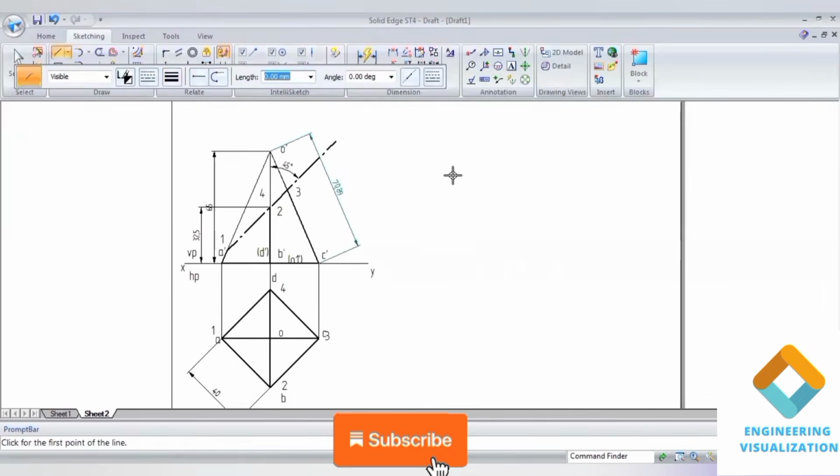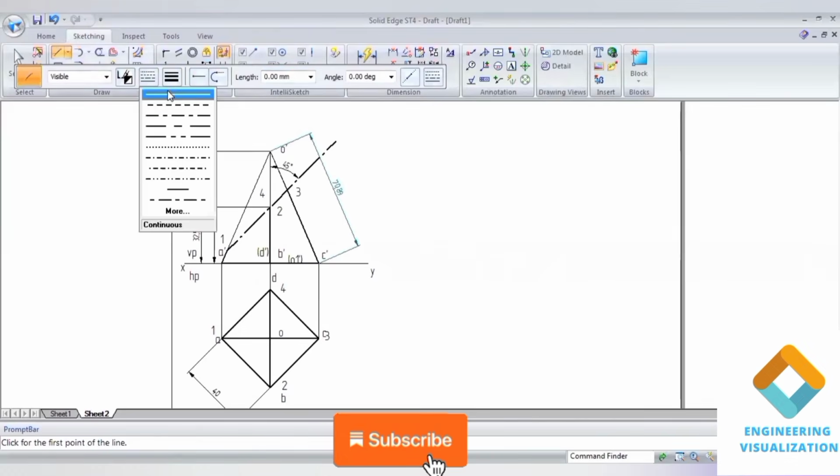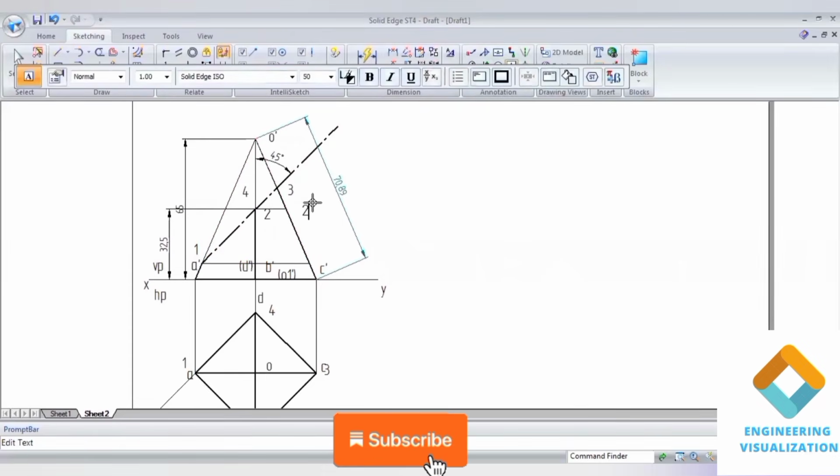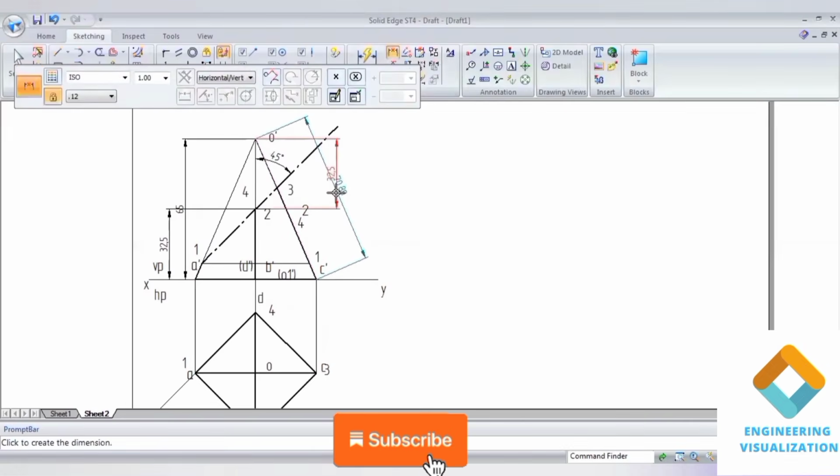For the same length, we'll be drawing a line. Now we need to transfer all these cut points onto the slant edge length. 1 and 4, this is an important step, guys. You should do it. 2 and 4, and this is 1. 3 is already there on the slant edge. You need to measure these lengths because we need to cut the arcs on the slant edge when we are drawing the development. We should know these dimensions. The slant edge lengths we need to find out.